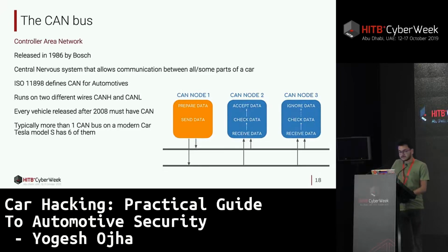So what happens is, when a bit is transmitted in a CAN bus, the signal will simultaneously broadcast one voltage higher and one voltage lower. When the CAN bus is resting, the voltage that you see is 2.5 volts. But when you send, depending on what kind of data packet is sent, it's going to be either 1 volt higher or 1 volt lower. That's going to be either 3.5 or 1.5 volts.